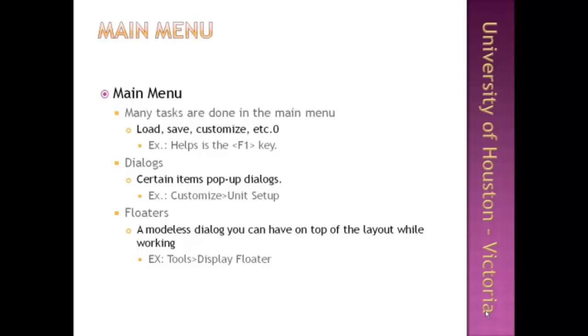Alright, now the next step is to learn about what we have in terms of the menus and different options that we can choose from the layout to work on different things. Basically, like every Windows program, your 3ds Max program has a menu across the top, which is called the main menu.